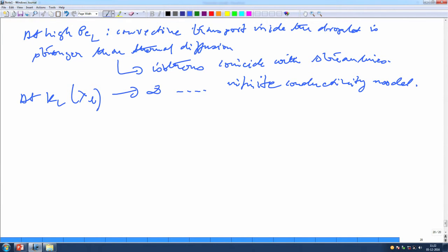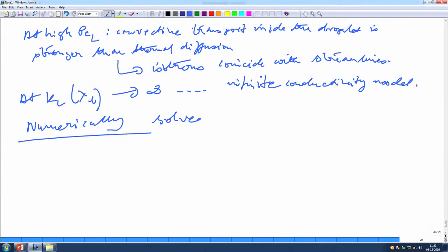So, this particular equation, there is no way that you can solve it analytically. So, you have to solve this numerically. In the next lecture, we are going to see what the numerical outcomes of these processes are. Numerically these are solved, they cannot be solved in any other way, but we have shown from the main governing equation what you can expect. You can expect that your streamlines and your isotherms should kind of match each other. That is the case when you have a high Peclet number.